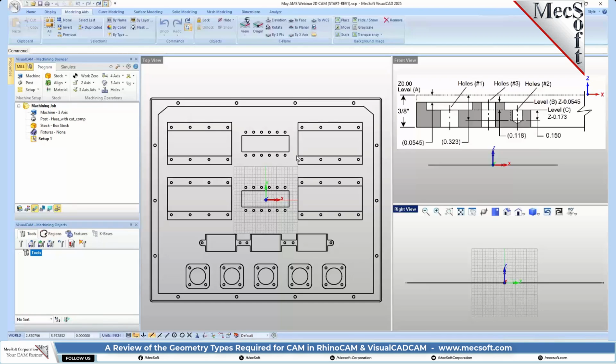In 5-axis, you need either a surface or a mesh similar to 4-axis. It's a little bit more to understand in 5-axis, because if you do continuous in the index 5-axis where you're rotating in planes, that will revert back to the requirements of whatever you put in that indexed fixed orientation. Drilling, 3-axis, revert back to those requirements. For 5-axis, if you're going to do continuous 5-axis or surface milling, you do need to have a surface, obviously, or you can do it with a mesh.